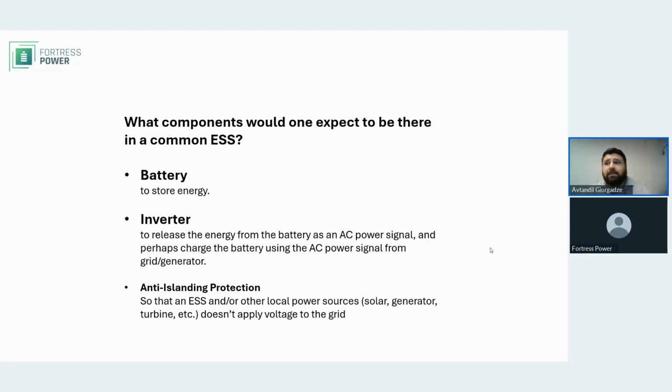The only thing that I could think that outputs AC electricity naturally is if you have a rotor and a stator and you have a rotating magnetic field. That's when really the AC occurs naturally. In all other cases, when we're talking about some kind of chemistry based energy generation or energy storage, we're talking about DC. So an inverter is needed to invert that DC to AC electricity so that you can power your appliances, which happen to be AC.